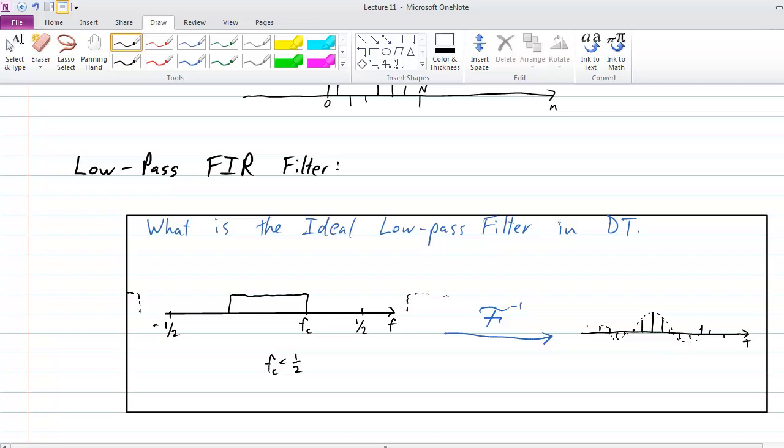So it's not always going to be the case that you get the same pair as you got in continuous time. You actually get, if you have a rect in discrete time, what people refer to as the discrete time sinc. Instead of a sine x over x, it's a sine x over sine x of different frequencies. Okay, so this is something to be careful about. It wasn't just for fun that we verify this, but